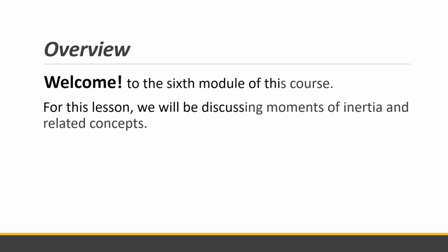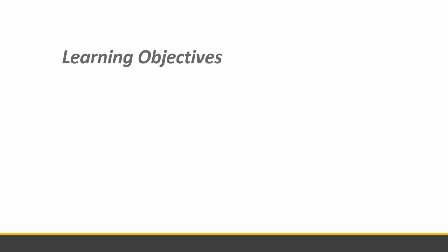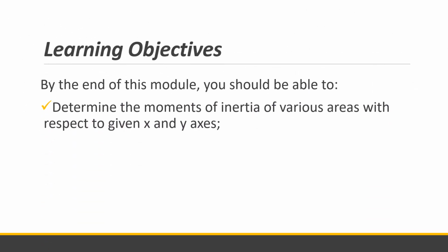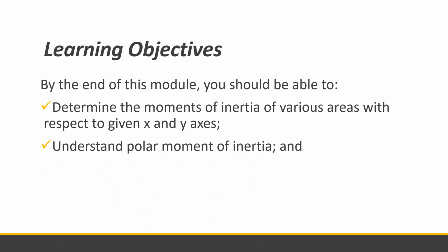So for this lesson, we will be discussing moments of inertia and related concepts. Hopefully by the end of this module, you should be able to understand and determine moments of inertia of various areas with respect to given axes, and understand polar moment of inertia and the parallel axis theorem. So this is all used to determine the moment of inertia of various shapes.